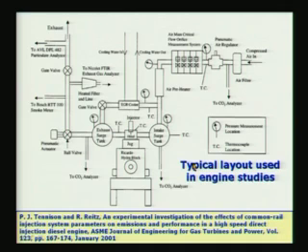So with this background, you can see also that we will be measuring the power output of the engine and various quantities. For example, we may operate the engine at various speeds, and how do you do that? You have to run this engine at various speeds, and also allow some of the output to vary by loading the engine. That means that we are going to subject the engine to a load.